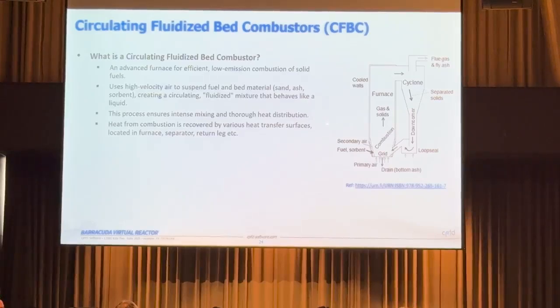So it is fuel agnostic, as long as you can make sure that the fluidized bed is operating properly, which essentially means that you have a well-behaved circulating system, such that there's good mixing going on, which ensures no hot spots and even heat distribution. Once you do that, from a CFB, essentially there are various heat recovery points to recover the heat from the combustion process that can be used for power generation, and so on downstream of it.